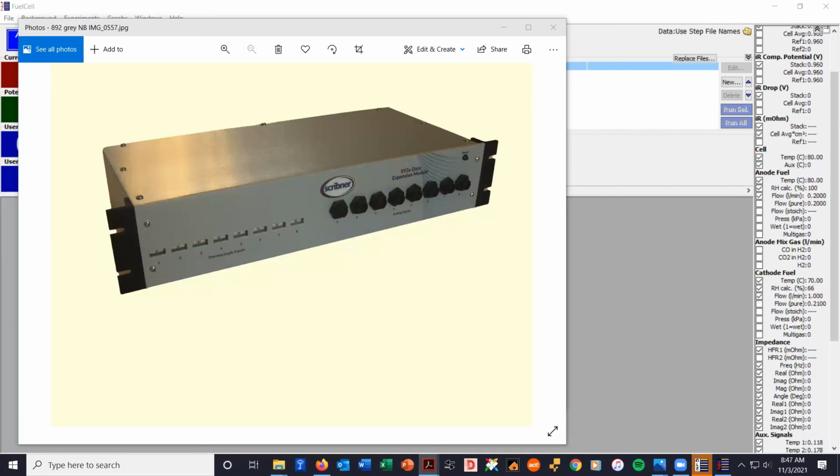Another question, referring to your flow bench schematic for the 840. When you were explaining the gas mixing unit, you said that if there is a corrosive gas, we have to do additional plumbing so that it goes directly to the cell. Can the gas backflow to the cathode humidifier? Is there a possibility?